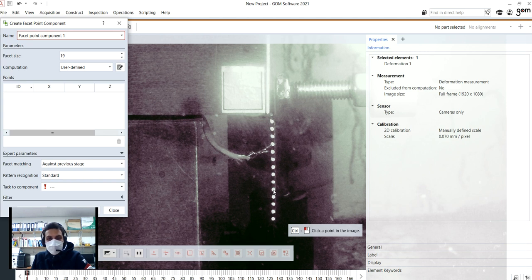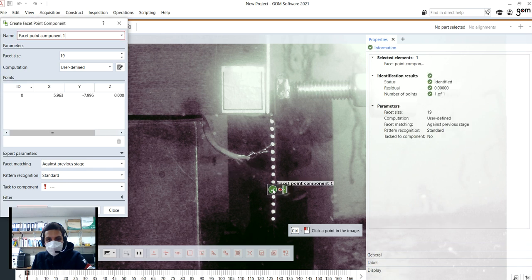So before scrolling on the white surface or white circle, you have to press Control and you will find the pattern quality. The pattern quality is quite important, because you can see if I scroll the points here, the pattern quality is changing quite a lot. So I'm going to check for the highest quality I can. You can see here there is 5.8, so I will check 5.8 here.